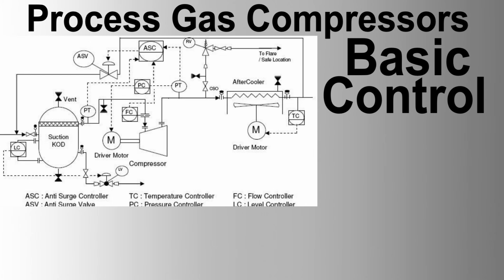8. Integration with other systems. A. Safety systems. Emergency shutdown (ESD): integration with ESD systems to ensure safe and rapid shutdown during critical conditions. Overpressure protection: ensure the system is protected against overpressure conditions using relief valves or similar mechanisms. B. Maintenance and diagnostics. Predictive maintenance: use vibration and other real-time data to predict and prevent failures. Diagnostics: advanced diagnostics through the DCS to identify and troubleshoot issues.